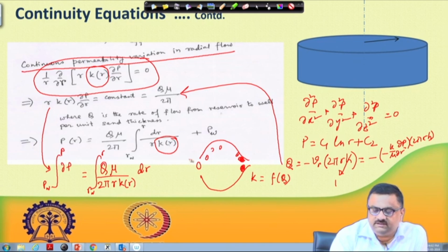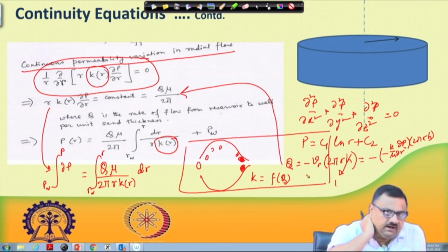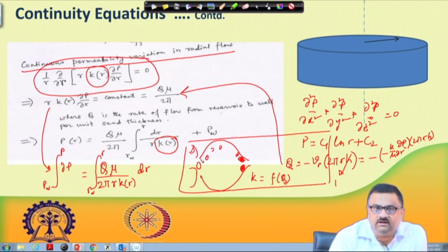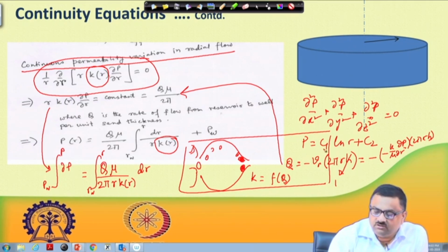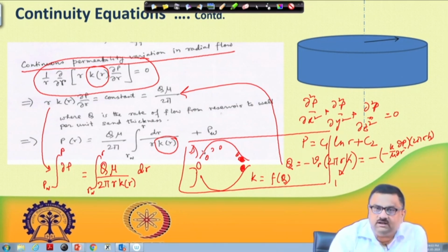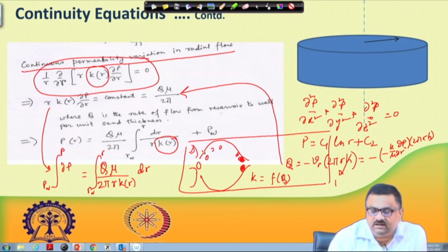So, what you would essentially see is that if this is the bed, this part of the pores have encountered more cumulative flow, more fluid has passed through this at a given time compared to this side. On the downstream side less fluid has passed through at a given time. So, that means there is less possibility of deposition of such suspended solids, and you will find that automatically you will be creating a permeability gradient in these.